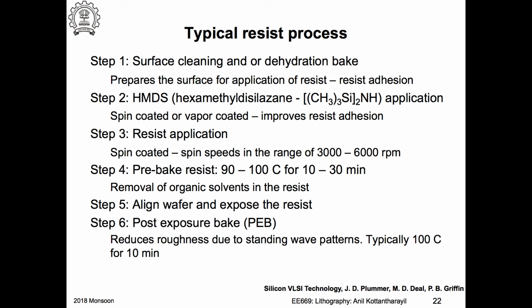Okay, if you use really very fast spinning, you may get very thin resist. In fact, the photoresist will also splash around, so you actually do this process in a closed chamber. And the photoresist is sticky stuff, so after some time the solvents will evaporate and so on and so forth.